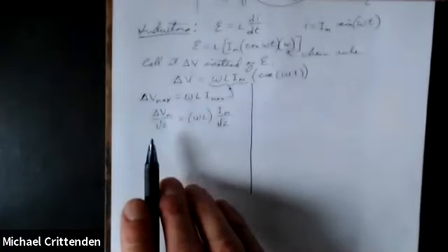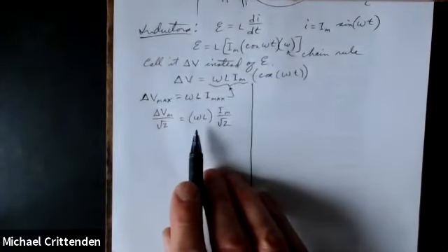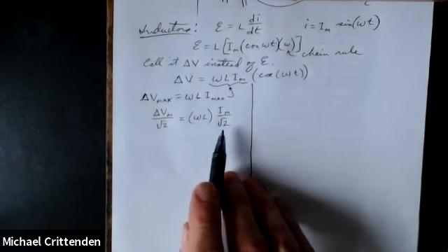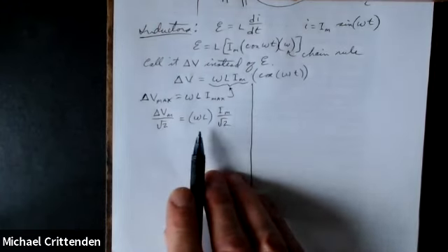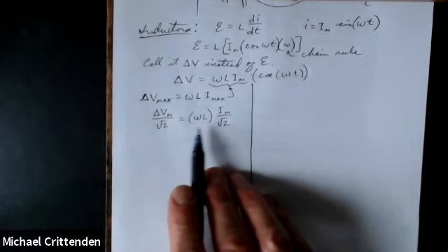So Ohm's law says volts equals something measured in ohms times amps. And this time, when it's an inductor, the something measured in ohms equals omega times L.